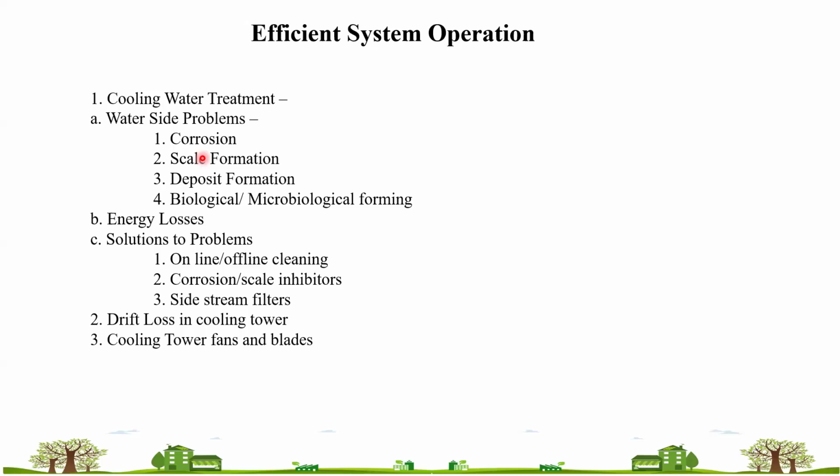Then there are water side problems, biological or microbiological formation, meaning algae, bacteria and fungi formation inside the cooling tower. That formation blocks the nozzles or the fills.